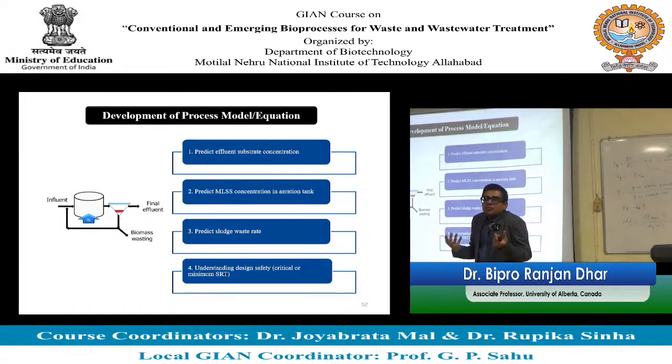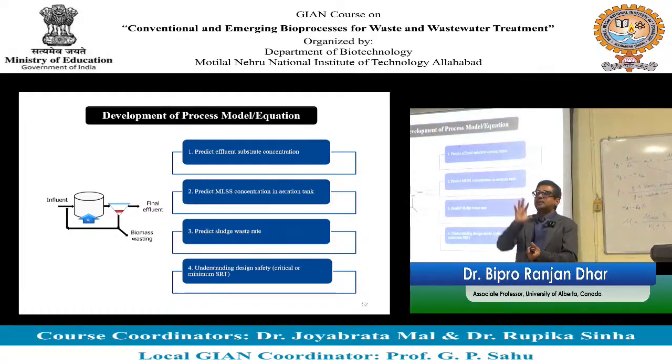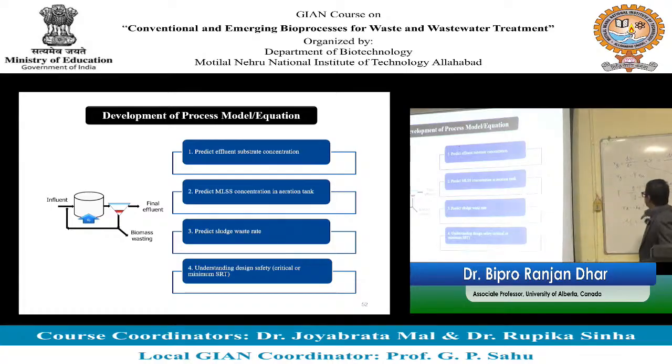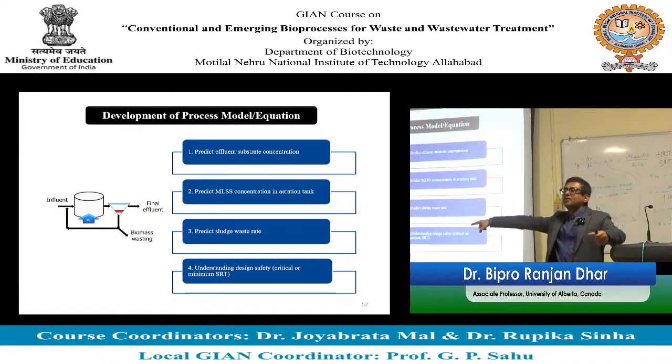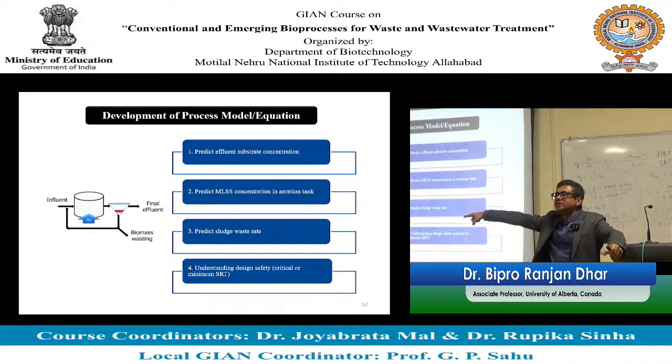So what if we have an equation, if we have all the kinetic information and the operating condition like SRT, where we plug in the SRT and all the kinetic information, the value for mu max, the value for KD, the value for yield, and we can estimate the effluent concentration, that's going to be a very useful tool, right? Instead of doing experiments, I can put some residence time in there and predict what would be my BOD concentration in the effluent, right?